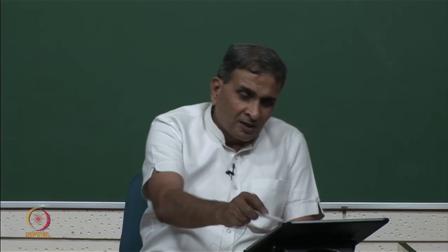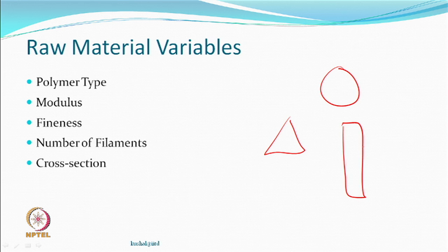For example, bending this material in this direction is easy compared to bending across this. So, rigidities will definitely play a role, and dimensions too. Density is the same, linear density is the same, number of elements is the same, fineness is the same, modulus of the material is the same, and still, because of the cross section, you will get different results. Then there is inter-fiber friction.